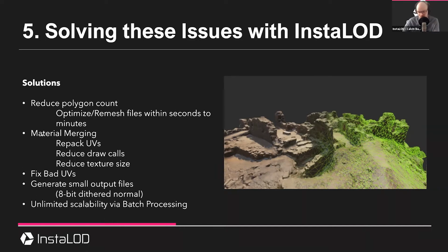This is first of all going to repack the UVs, because oftentimes with scan data, you can get UDIMs. Now, whilst UDIMs are nice, they're not really practical, especially for VR. We want to be able to pack all of the textures together. We want to pack the UVs together. Ideally also have new good UVs, because UVs that come from scan data are most often just complete trash.